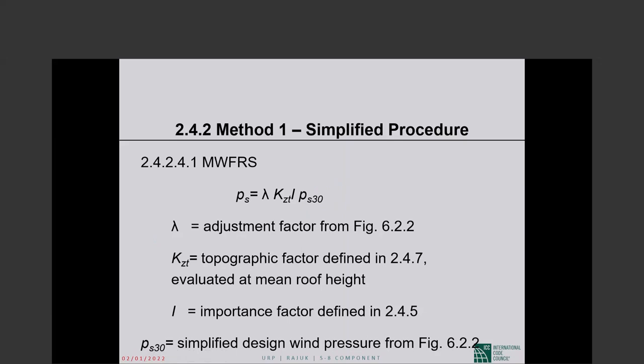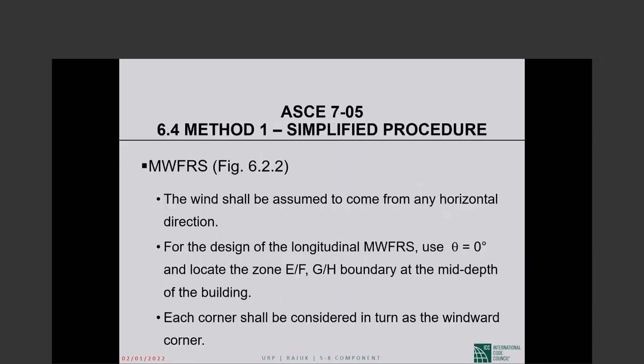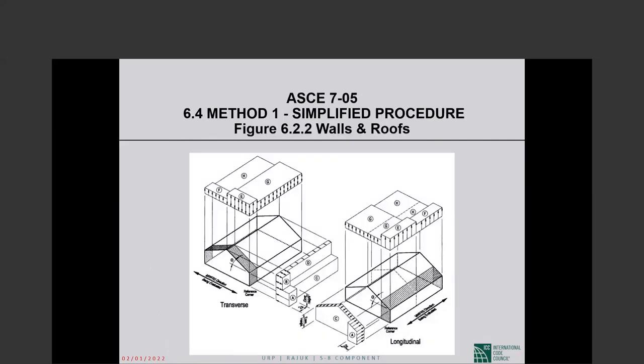If you're designing a hospital, it will be 1.15. The K sub ZT factor if the structure is not on level ground. If it is up on a hill, K sub ZT shall apply. And the gamma is a conversion factor, because this method, I'll show you where...